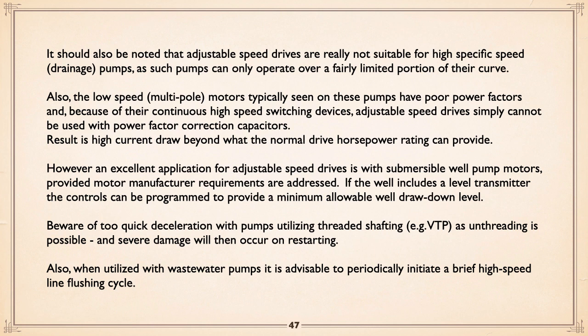Now, one thing: beware of too quick deceleration for pumps using threaded shafting, like vertical turbines. If you set the ramp down time too quick, instead of coasting along merrily, which vertical turbine pumps classically have done, they do their own thing as they coast out, the motor being most of the inertia anyway.